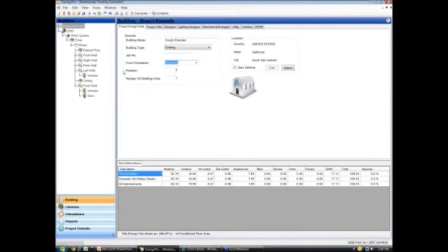Now there's another line down here that says rotation. You guys, if I put in here 90, what it's going to do is it's going to change every wall orientation. Everything that has an orientation in my building tree, it's going to add 90 to it. I can tell you, if you're a power user, use rotation.